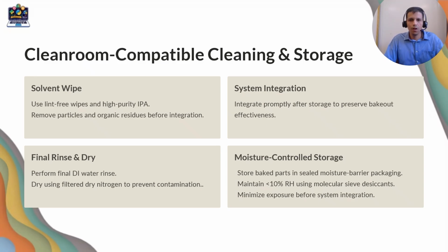We always need to use lint-free wipes to wipe the part, and also be careful about how we are storing the part. Always try to use a dry place and try to bag it. This is the standard method followed by some industries to reduce contaminant particles on the surface. It's necessary and useful to follow those processes.